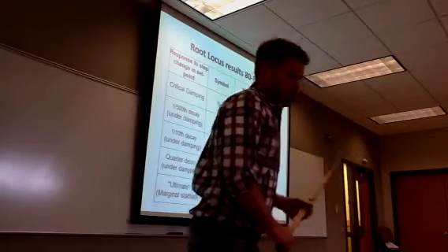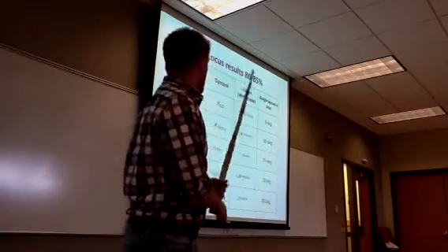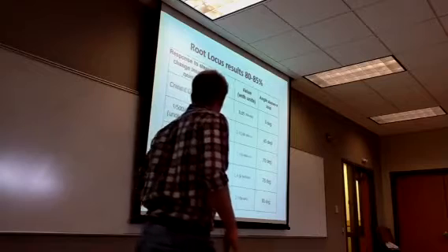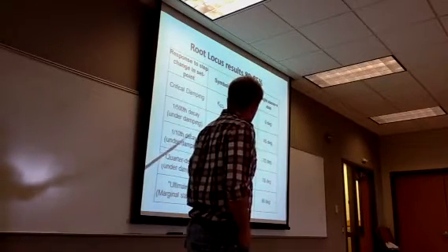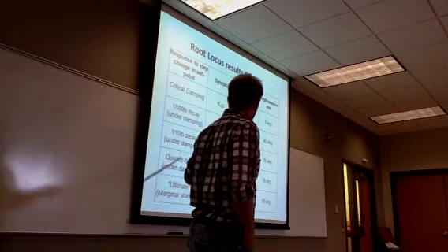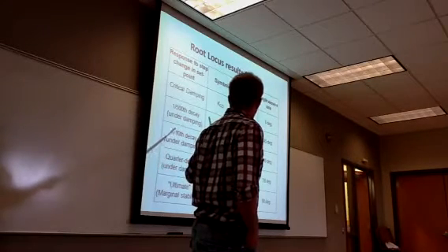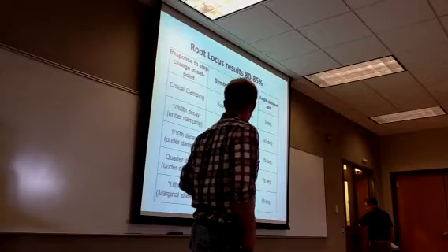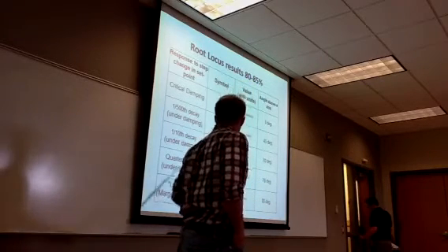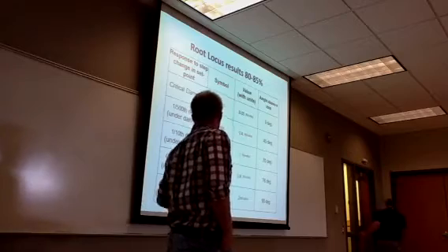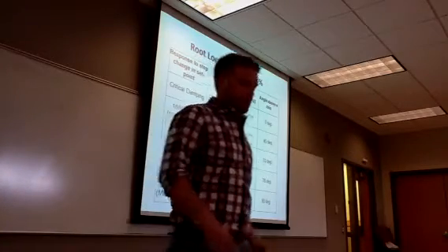These are some results for 80 to 85%. As you can see, the Kc was about 0.05. The 1/500 decay is 0.4. The 1/10 decay is at 1, and the quarter decay is 1.4. Ultimate is around 2.